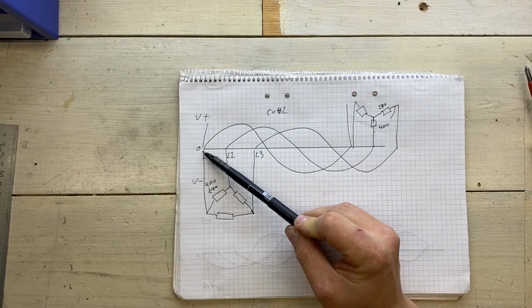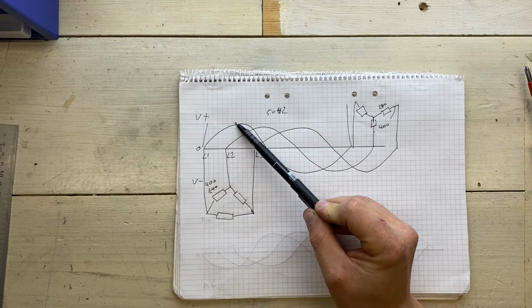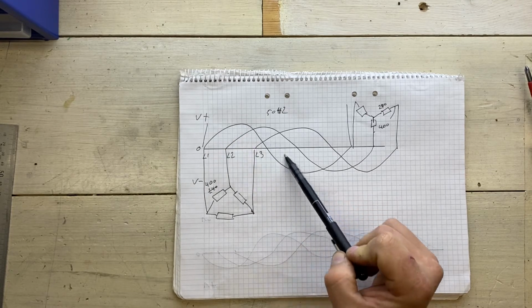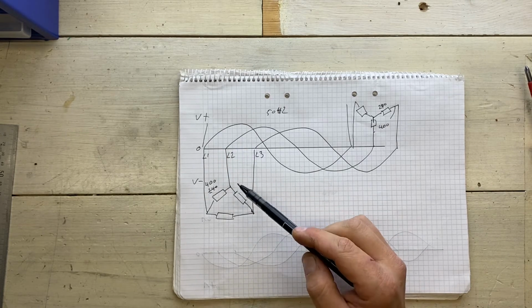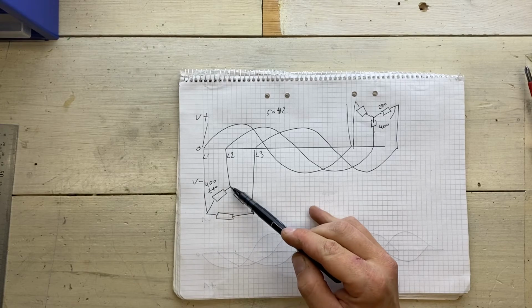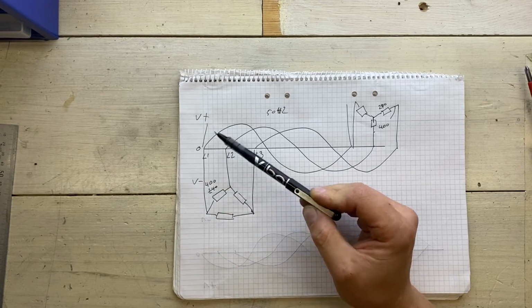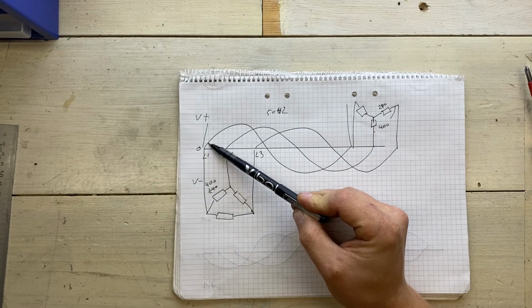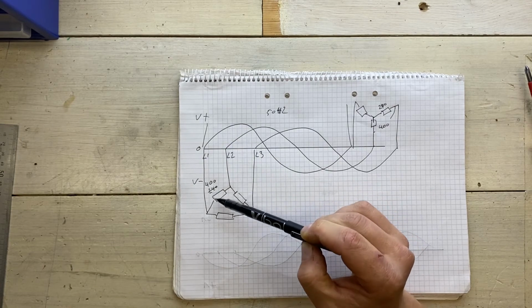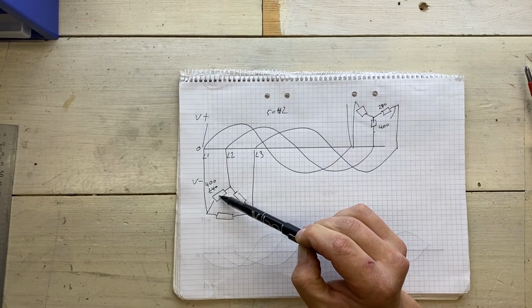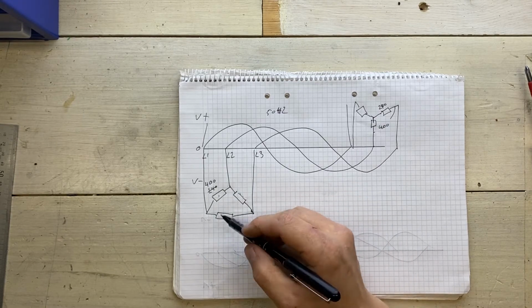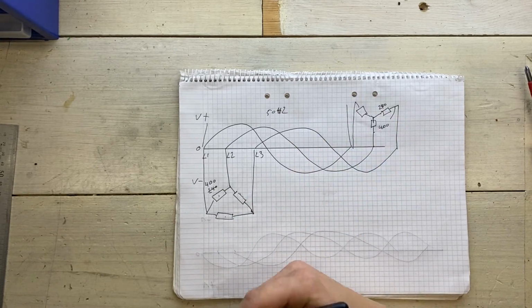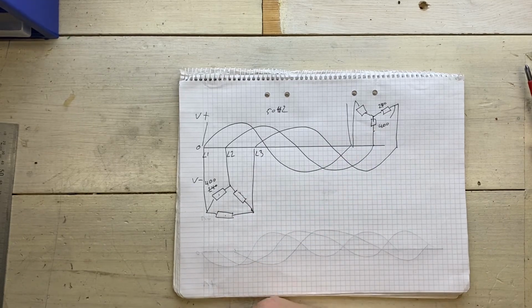And since the power is constantly changing between positive and negative, this is what creates the rotating magnetic field. Because we will energize each one of these coils in sequence. So when this wave increases, the magnetism increases in this coil, and then the next, and then the next, and then the first one, and then the next one, and so on. And this creates a rotating magnetic field, which of course gives us angular momentum and a motor.